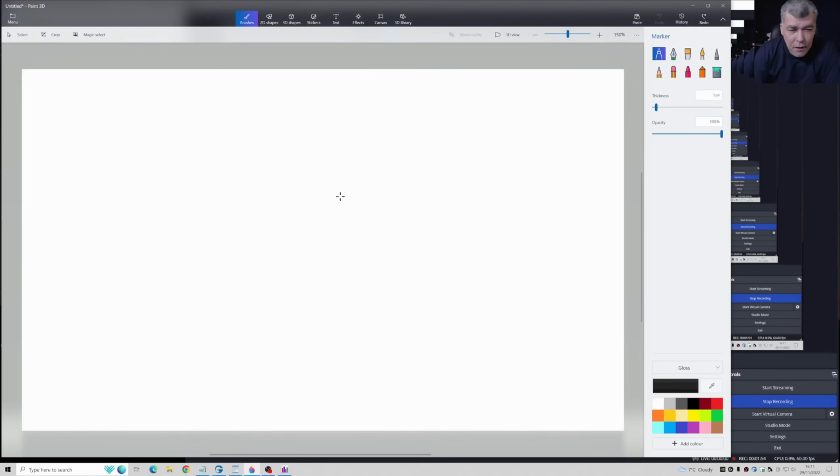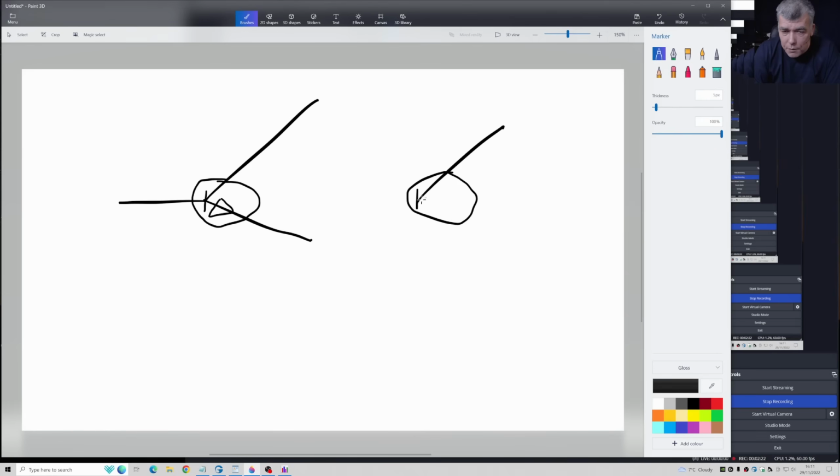Now, first, the symbol of a transistor. Yeah, we are speaking of bipolar junction transistors. So that's the symbol of the transistor. If the arrow is pointed out, this is an NPN transistor. That means it has two N junctions and one P. The other transistor you can find is with the arrow pointed inside. This is a PNP transistor. So what's the difference between a PNP and NPN? The difference is the current is flowing in a different direction. Now let's go back to the first one.